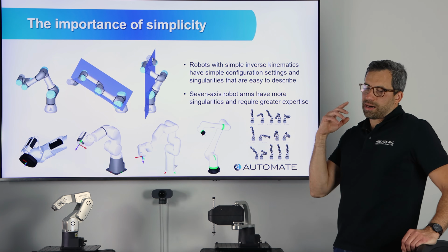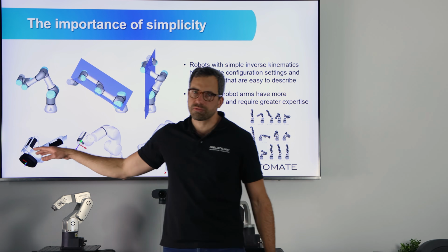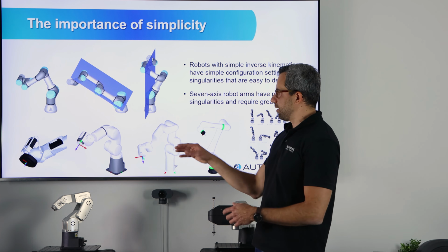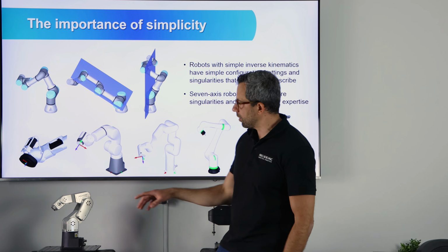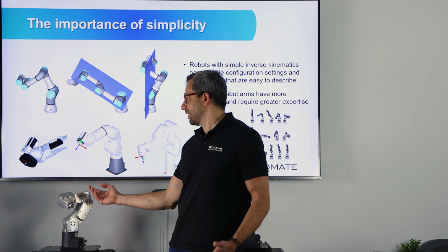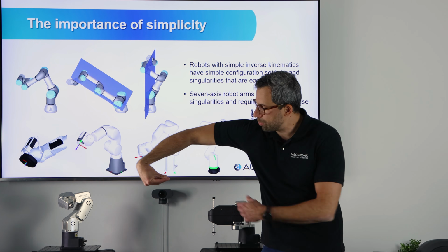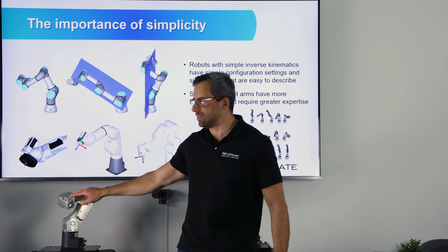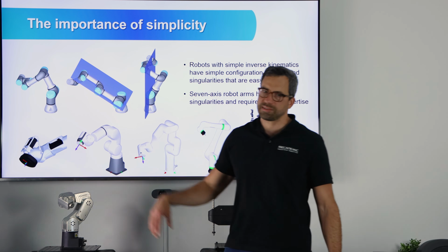But there are more and more architectures where, sometimes, you have no choice. If you have painting robots, they always have what we call a non-inline wrist, basically a wrist where the 3 axes don't intersect. This is because with this kind of wrist, you have a small range of motion for θ5. But for painting, you need to be able to get inside the body of the car and do this kind of motion, so you cannot do it with an inline wrist. That's why for some applications, you need this kind of wrist.